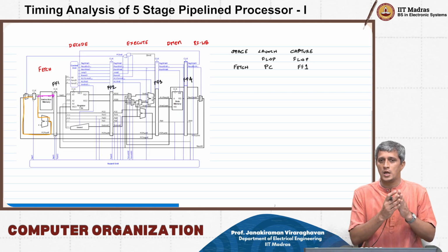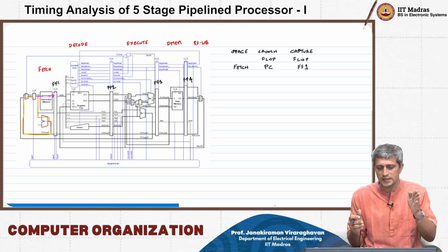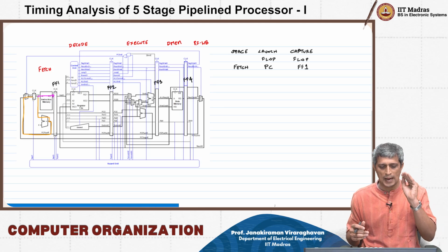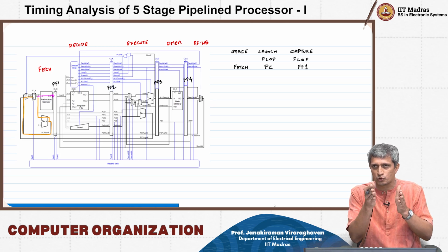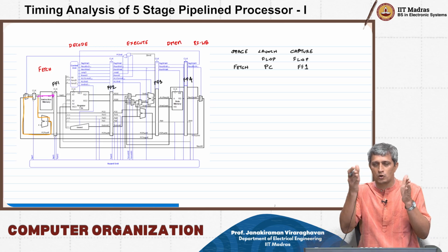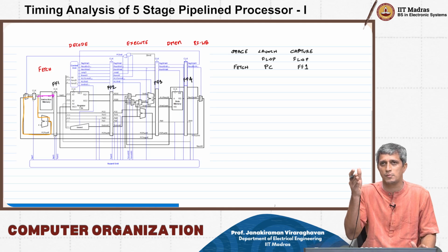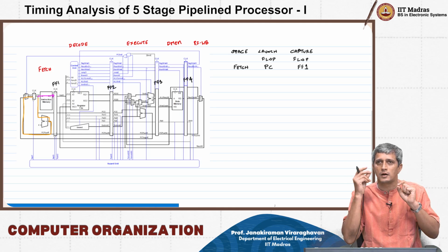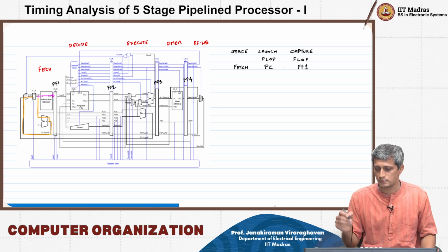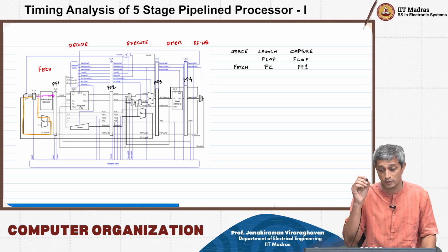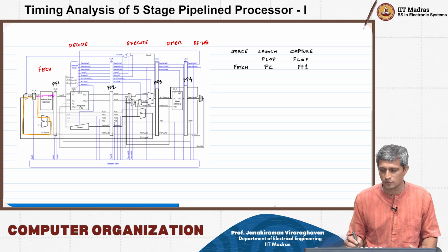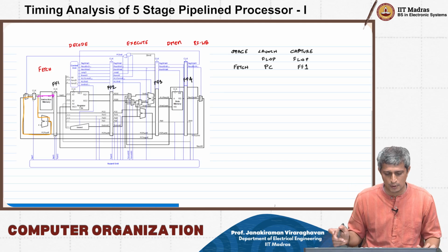Anyway, the critical path for this fetch stage is obviously originating from the program counter, giving the address to the instruction memory. You are reading that out onto the data bus of that memory, RD bus, and then you are putting a flip-flop out there. Therefore, the capture flop is the FF1 flip-flop. So the path in magenta is what I would call the critical path here.